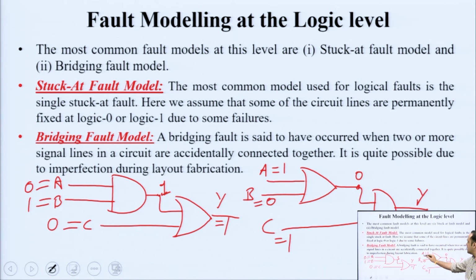Sorry, this I have simulated deliberately to get a 1 here, but I am getting a 0 as the output. So, this is a stuck at 0 fault, and this test case 1 0 1 is a test case which helps you to simulate or create a model to identify and locate a stuck at 0 fault.